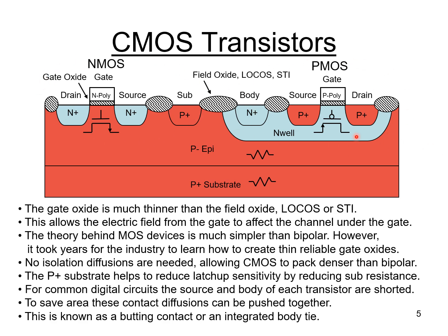The NMOS transistor has an N plus region for its source and drain with a P body, and the PMOS transistor has just the opposite. It has P plus source and drain with an N body. But aside from that, the two transistors are very similar to each other. They're just sort of opposite polarities. I've drawn in schematically what they look like underneath each of the associated transistors there.